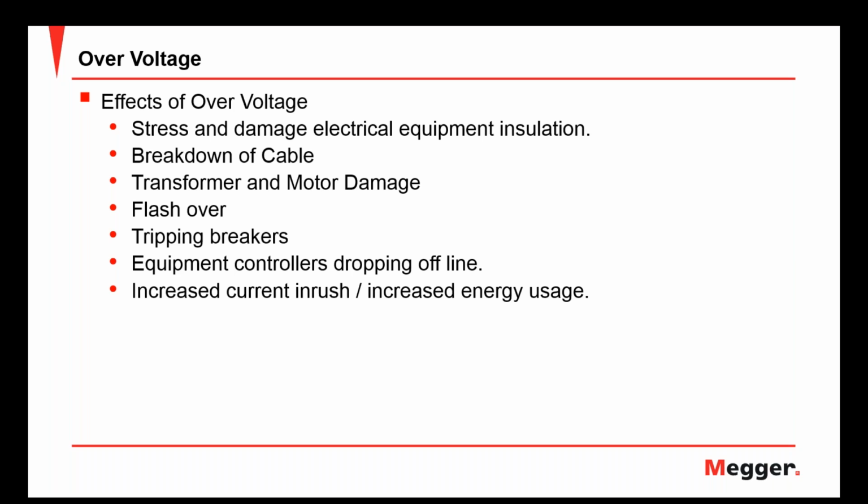So in any of these cases, we do want to look at overvoltages. And also in motors, when we go to turn the motor on, we have a current inrush. If the voltage is sitting too high, you can get excessive current on that inrush as well.